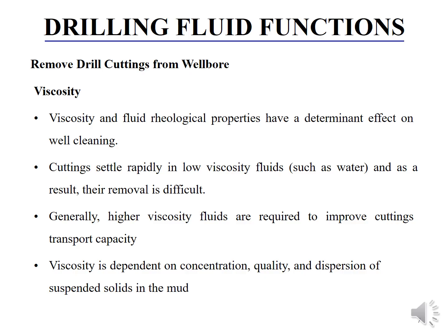So one of the main factors is viscosity. Viscosity and fluid rheological properties have a determinant effect on well cleaning. Cuttings settle rapidly in low viscosity fluids such as water, and as a result their removal is very difficult. Generally higher viscosity fluids are required to improve cuttings transport capacity. Viscosity is dependent on concentration, quality and dispersion of the suspended solids in the mud. So viscosity plays a major role in the selection of mud.